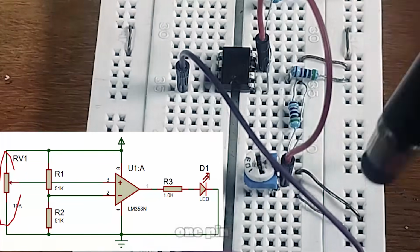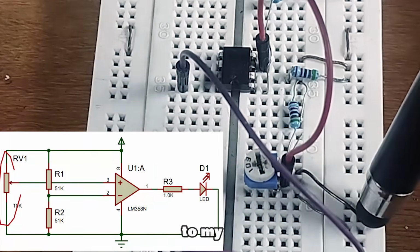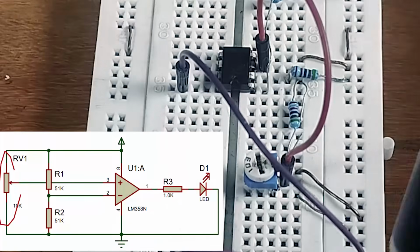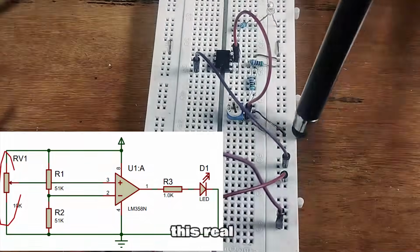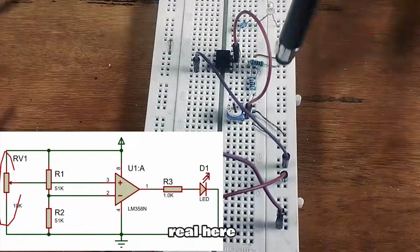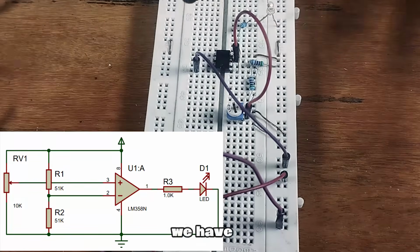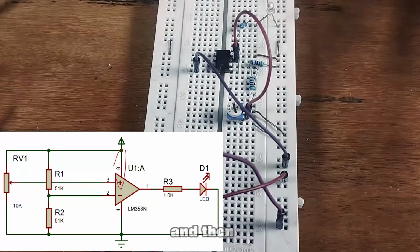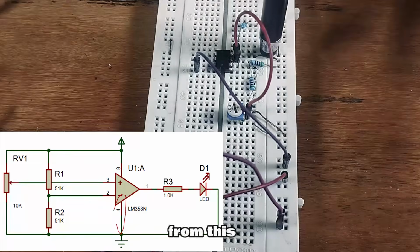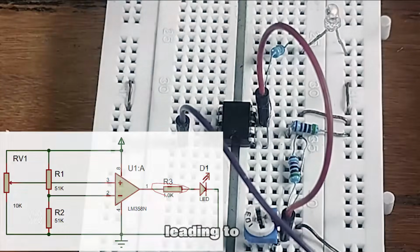Okay, and then one pin of the variable resistor is connected to my negative and the other pin is connected to my positive. Of course, the positive is connected on this rail, negative is connected on this rail, positive, the second rail here negative. All right, then we have this pin, the positive pin of the op-amp, and then we have the negative pin to be this last pin, which is connected to the negative from this jumper. Then we have this resistor on the output leading to our LED.